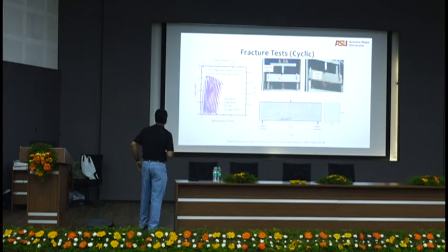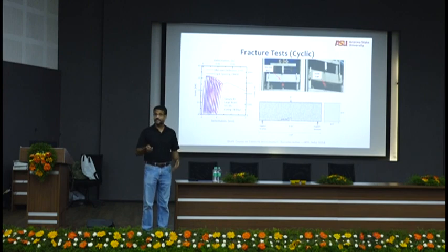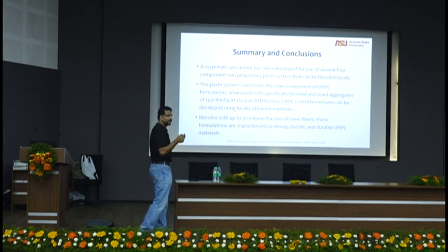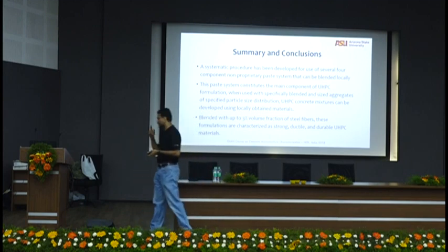And then cyclic load testing, because it's subject to fatigue. The connections are fatigue connections, so we need to look at some of these cyclic loads also. And you see here 30 kilonewton loads, very high cyclic load. So we developed a systematic procedure, and the bridge has been implemented.